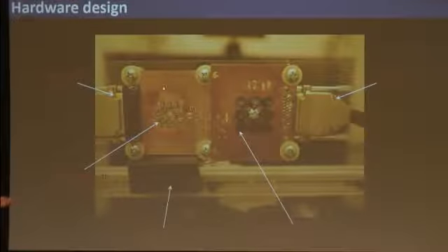But we decided to do a different thing. So we're using here MEMS microphones typically intended for use in cell phones. These microphones are typically intended to go up to maybe 10 kilohertz, but it turns out that they also hear 40 kilohertz. Their polar diagram should be omnidirectional, which at 40 kilohertz, with our design, apparently it's not. I'll talk about it later. This is kind of a challenging point.